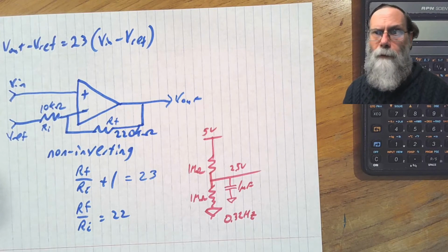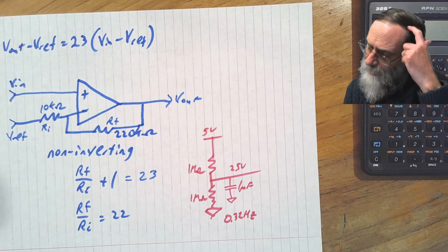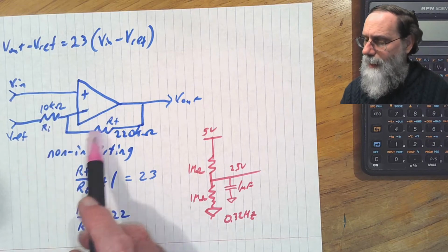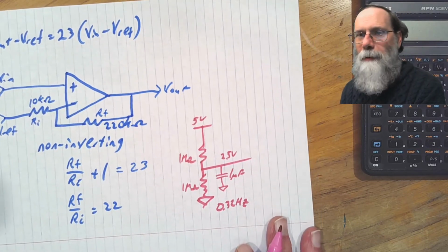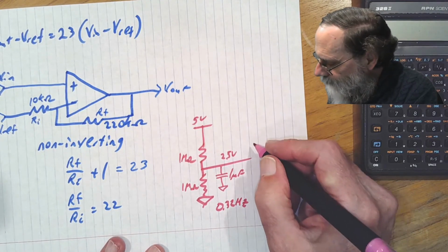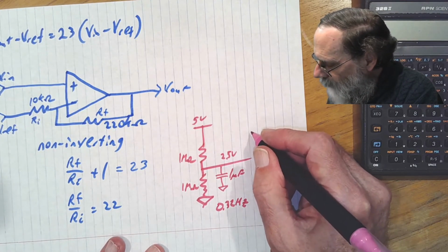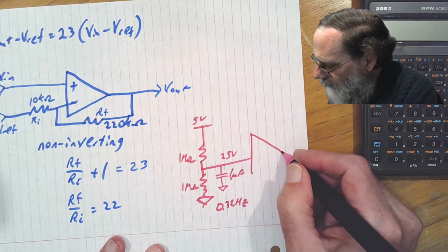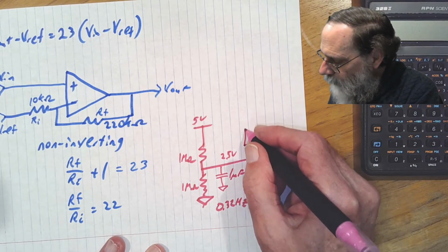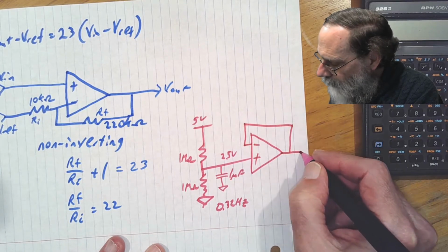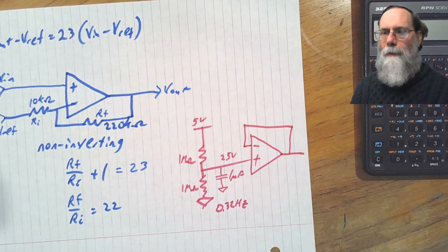So how do we get a gain of 1? Well, it's going to again be a non-inverting sort of amplifier, but we can do a bit of a trick here. We can put this into the positive input, and then for the negative input, we can just put a wire from VREF back.